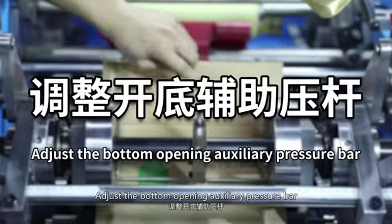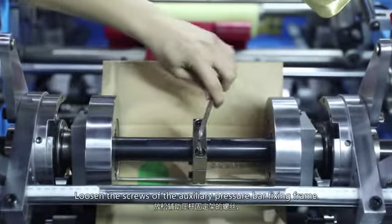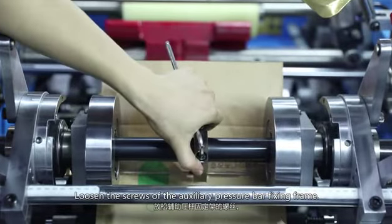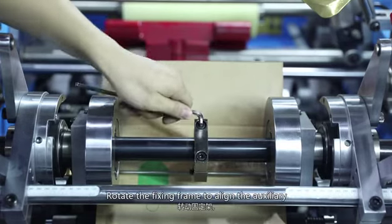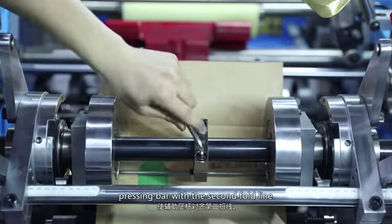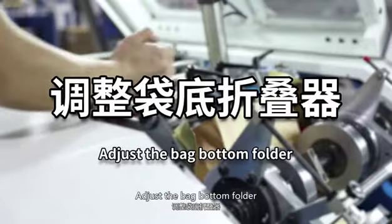Adjust the button opening auxiliary pressure bar. Loosen the screws of the auxiliary pressure bar fixing frame. Rotate the fixing frame to align the auxiliary pressing bar with the second fold line. Tighten the screws. Adjust the back button folder.